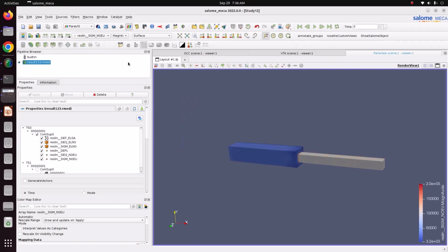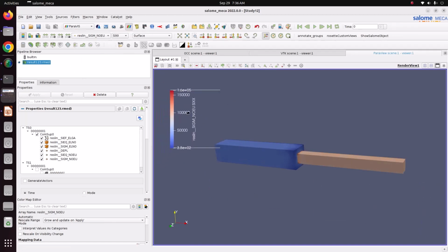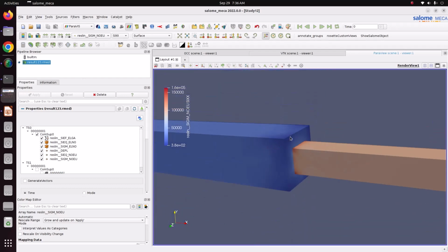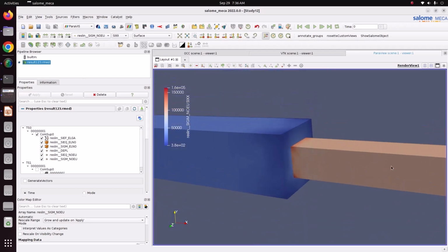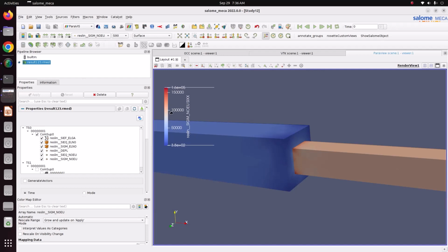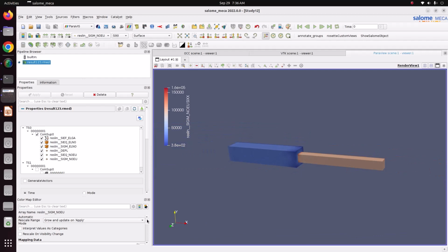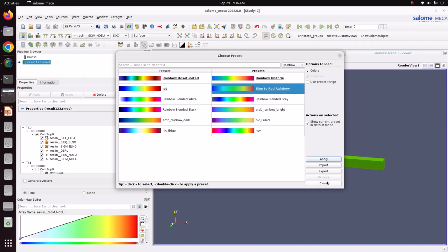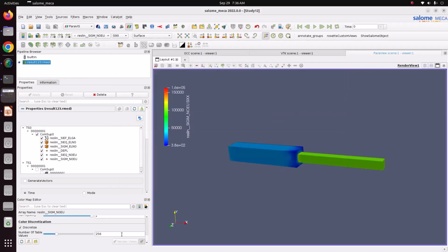So we can go for stress also. Here we are getting the maximum stress because of the contact. Just leave this contact, only check the results here. This value is around 1e5, the same value we are getting. To see the results in plots, just go into rainbow, blue to red, apply, close. Make this 12. See the stress here; this color matches with this color.